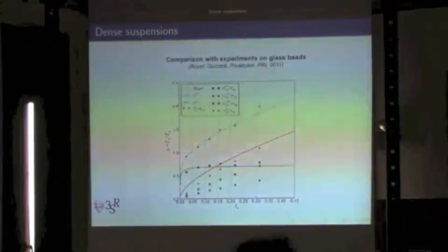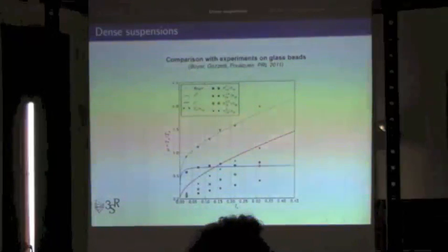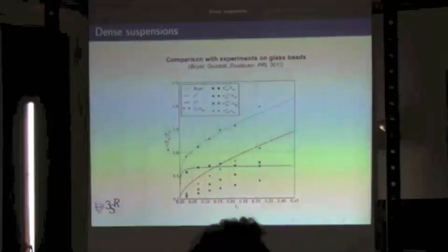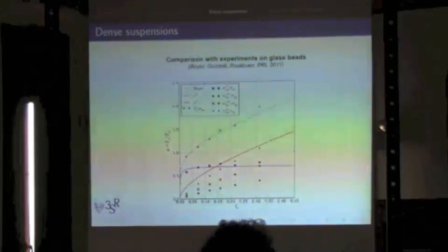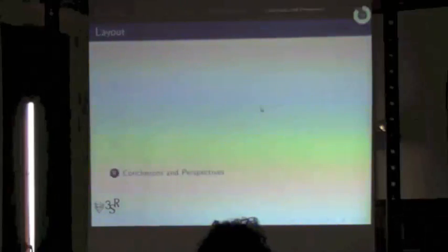Coupling, this is another thing. Physicists, they don't care about coupling. The transient state in the beginning is an experimental artifact. They never looked at that, but the thing is that we can simulate it. And for us it's very important, because imagine a debris flow going down a slope, and the slope angle is changing. So it's accelerating, decelerating, accelerating, so it's always transient. So you have a major effect of this coupling.